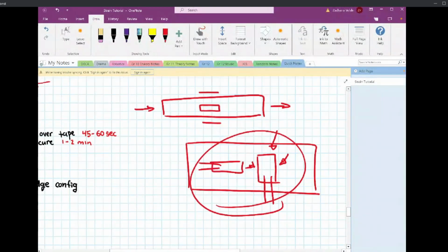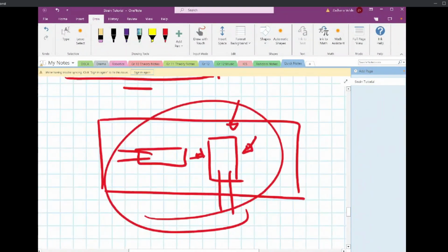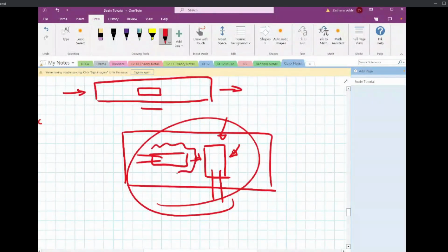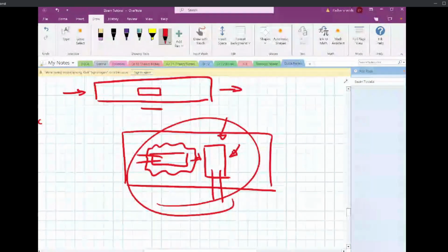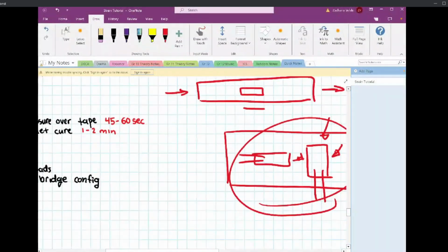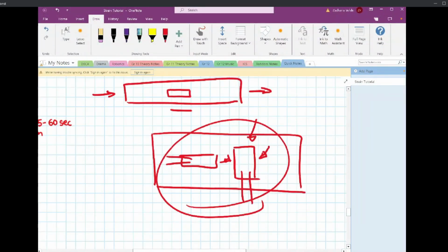One of the things with putting strain gauges close to each other like this is you're going to get CA glue here unless you get really good at it, or maybe you're even going to get it like here, right? And then you've got to clean that surface up before you apply the dummy one. So that's why, even though you want to get all your strain gauges put on fast, sometimes it's good to get all your principal ones on and then come back the next day, clean off the surface properly, and take your time and put the dummy ones on there too.